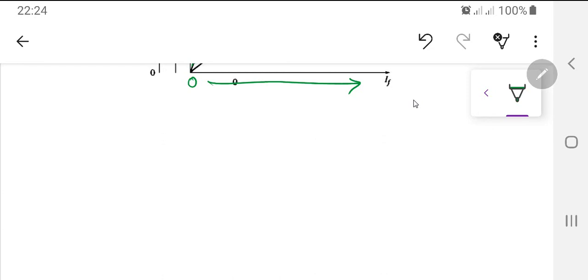Before we go on further, the article is divided into 3 parts. The first is the resistive load. This is very important, because in this article I am not going to assume that RA is equal to 0. I am going to draw the phasor diagrams with RA not equal to 0, so I am going to include them. Your book has phasor diagrams without them. At the end of this lecture, I will show you how those 3 phasor diagrams look without the IARA. The ones I am drawing here include the IARA vector.